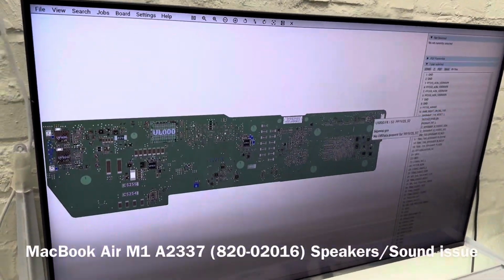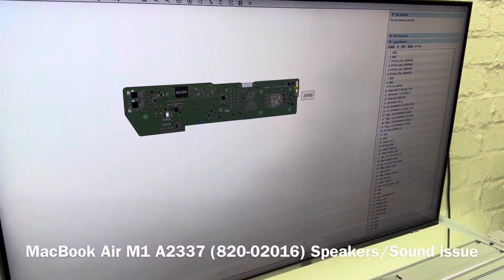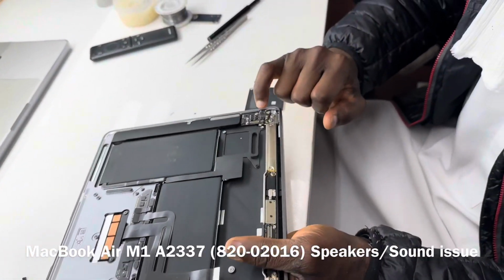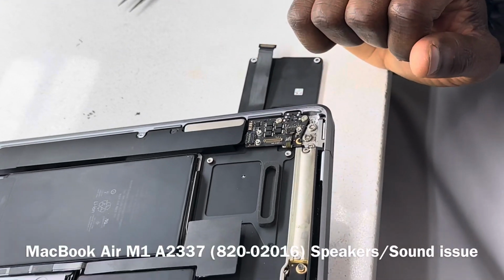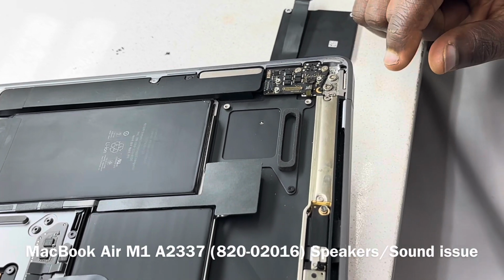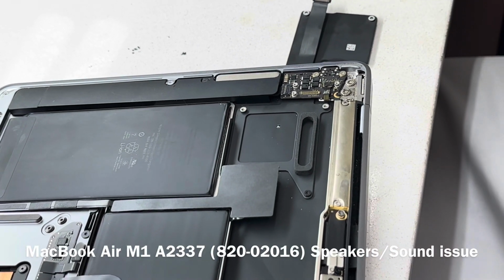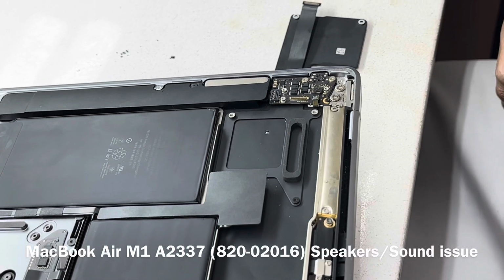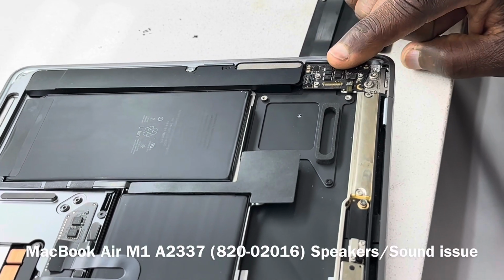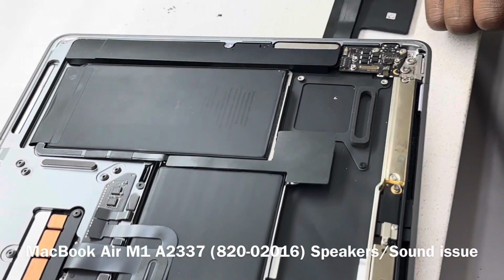So if we click on JE900, that is going to be the connector for this cable here, which connects to the audio board. This is our audio board. That cable there connects to the audio board, and the function that it performs is also audio, in addition to the touch function and the power button function as well. So this board houses one of the speakers. It houses the touch, the power button, which also houses the Touch ID.